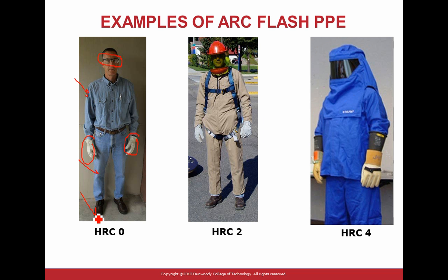But for 0, do you need that? You don't need that, but you should be wearing a cotton shirt, not a polyester or synthetic shirt. And I wouldn't just put the cotton shirt over top of the synthetic type, because the cotton shirt is rated to handle it, will insulate from the heat and not burn. I don't know if I have it for you guys, but I'll send you a description of what each category needs in terms of clothes.